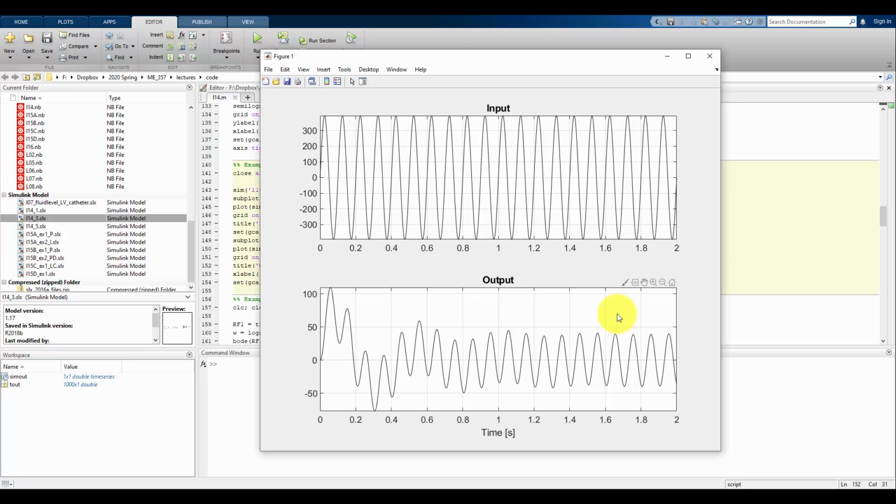Remember, when we're using the Bode diagram, all of our analysis in this course is based on the steady state response of our system. And so far, I've really just cut out what we call the transient phase, the stuff before it settles into this repeating sine pattern. So the first about 1.5 seconds of our output is in the transient phase. We're not looking at trying to model that. We're not trying to find the equation that determines that. After 1.5 seconds, now it's this steady sine wave.